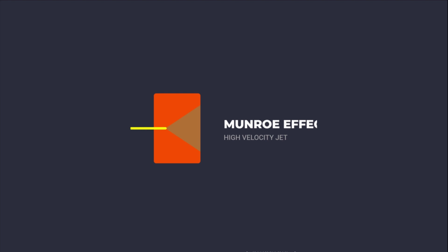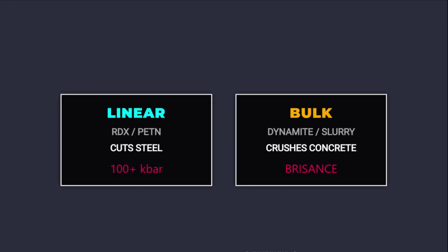Implosion relies heavily on the Munroe effect, utilizing shaped charges to focus explosive energy into a high-velocity jet capable of cutting steel or crushing concrete. Linear-shaped charges, typically containing RDX or PETN, are used to sever structural steel beams and columns cleanly. These charges create a focused pressure wave exceeding 100 kilobars at the point of contact.